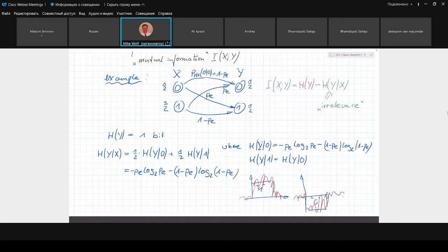Then we build an optimal detector for these waveforms using a minimum distance criterion. With a certain probability, PE, we get an error in our decision, because from this red waveform, we try to reconstruct the original information. Was it a 0 or was it a 1?